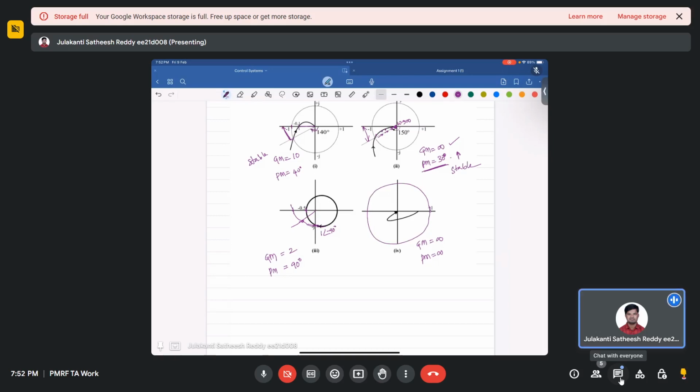Infinite means at any constraint, at any condition. So that means the gain margin and phase margin are not at all related. So you change any parameter in the system. Say you have some constant gain k, so you have k G(s) H(s). You are varying the parameter k. By varying k, the characteristic equation poles are always lying on the left of the S plane. So it doesn't have any role over it. You change this parameter, the system always gives bounded output for bounded input. So that means there is no relation.